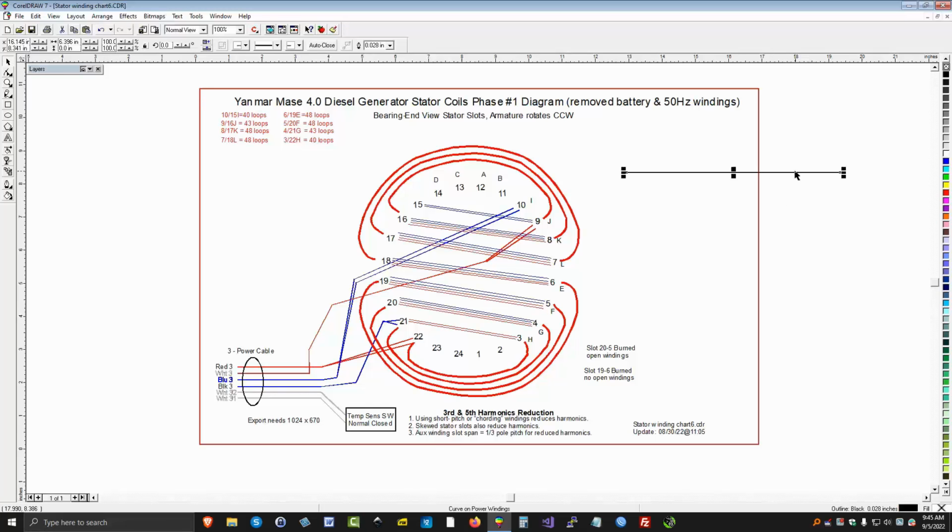Okay, we talked earlier about doing duplications. Let's do that for a second. Let's take this line right here, which is selected. We're going to Control D to duplicate it. Notice there was no, that's a bad example because there's no vertical offset. Let's change our vertical offset. One thing I don't like, when it shows you the line tool, you can't see the offset. I'm going to click off of that. Let's make the offset go up 0.1 inches.